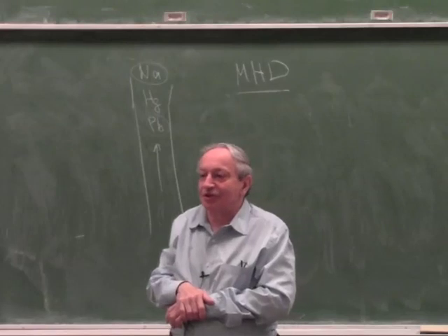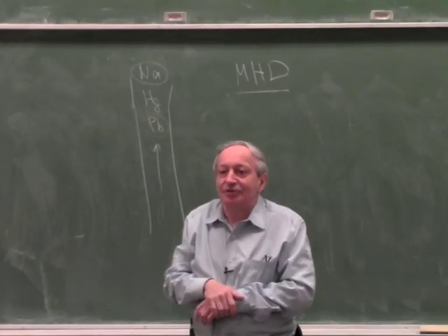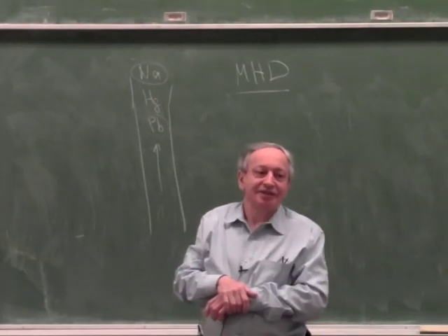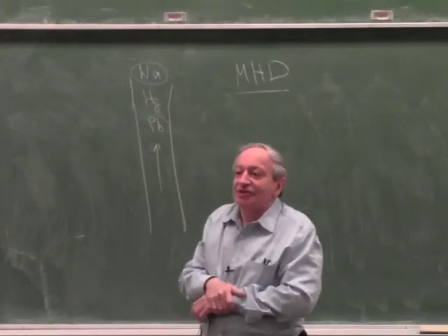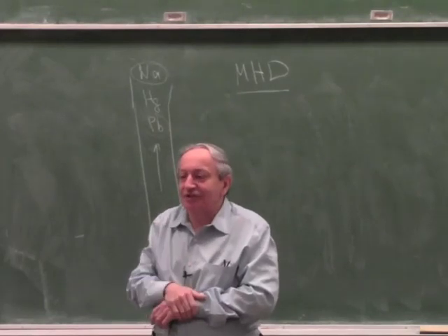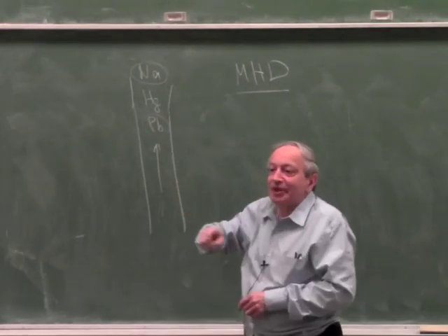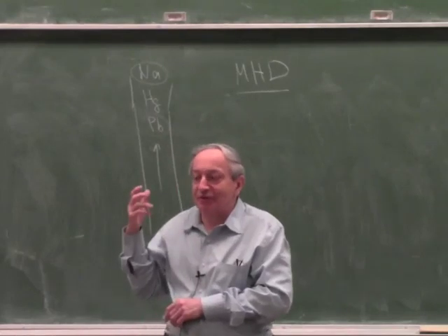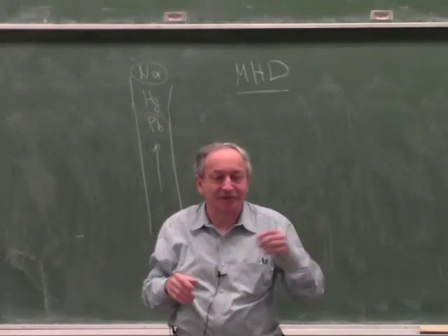Cooling systems, not just nuclear reactors, but other cooling systems, because you can carry a lot of heat out with molten metal. Okay, and there are many applications. Sodium melts around 100 degrees, so there are lots of applications where you actually want the fluid to be liquid metal instead of water, and it has all kinds of advantages. I won't get into it. So anyway, mercury today is used less, but there are some systems which use mercury as a working fluid. The early nuclear stations, some of them use mercury as a working fluid, again because it boils at a much higher point than water, so you don't need high pressures to transfer the heat.